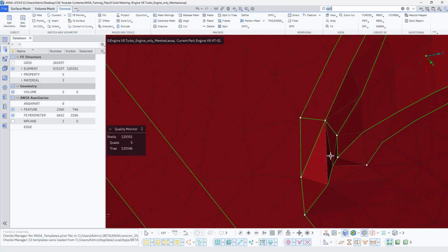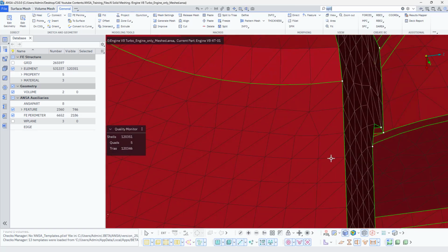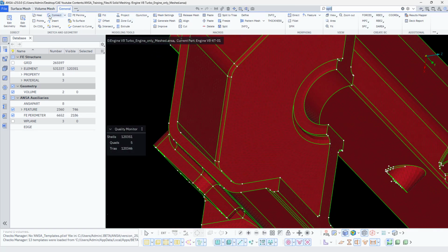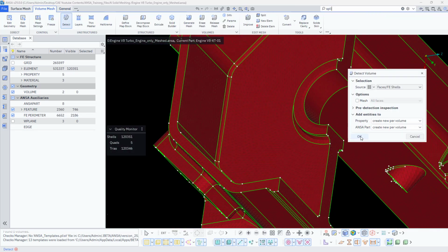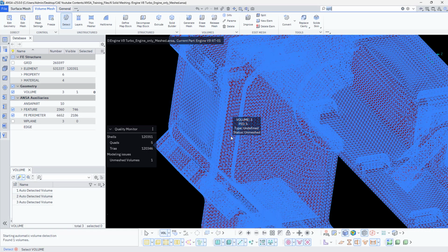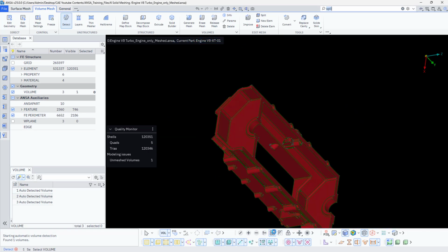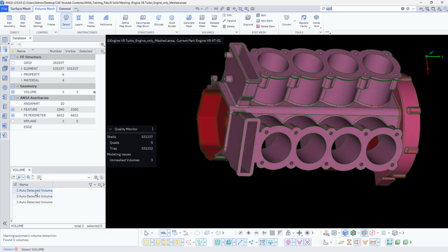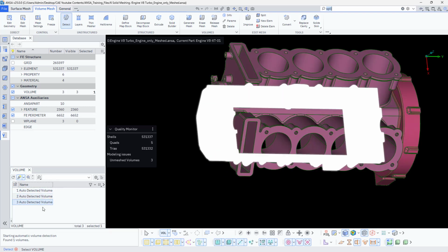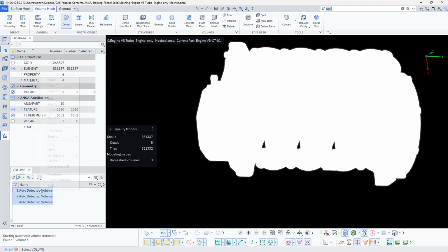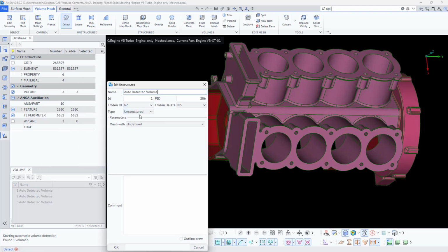Once you are doing this, I think you again need to carry out the quality check at these regions. Very important, guys. So in the interest of time, I think it has selected all now. Let's see, first, second and third. You can select these all, right click and use edit definition, so that it will ask you for the type. I would like to go with the Tetra FEM.